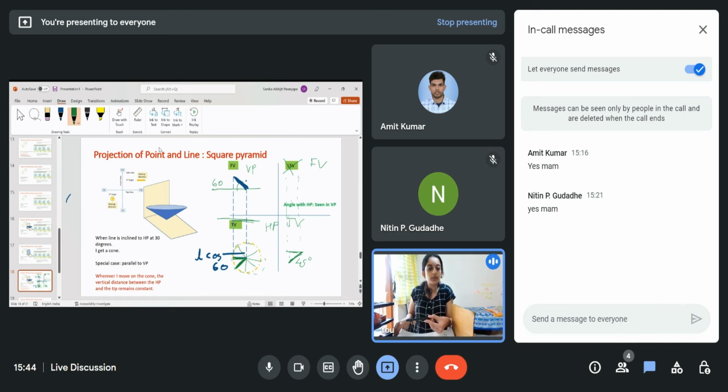Now let us consider this projected length. I'm putting dotted lines like this from this point and from this point, and I'm projecting it like this on the vertical plane for you to see in the front view. Because when I actually draw it, this plane is going to drop down like this, correct? So these vertical lines will come down like this.